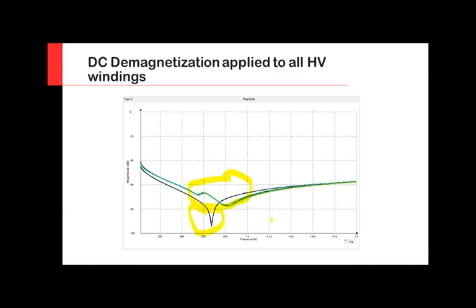So now it is on the same frequency with a minimum deviation in magnitude, but you're getting the same resonance point. One of the things that is interesting here is you can see that the first resonance is getting close to minus 100 decibels. And that is kind of typical on many transformers.